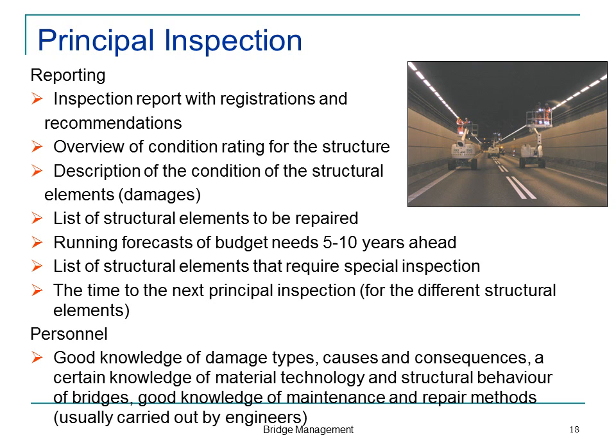Usually we have something so you can measure positions, and we would have a card like this with small stripes on. That's really to measure the crack width in the concrete. You place it up against the crack and you say, well, yeah, 0.15 millimeter width. Simple, robust, old-fashioned.